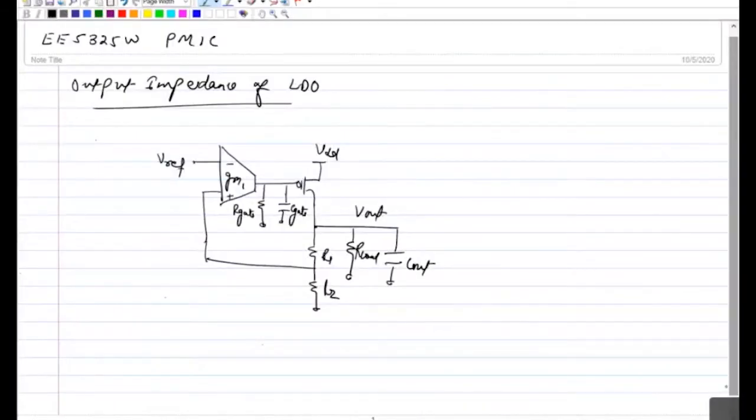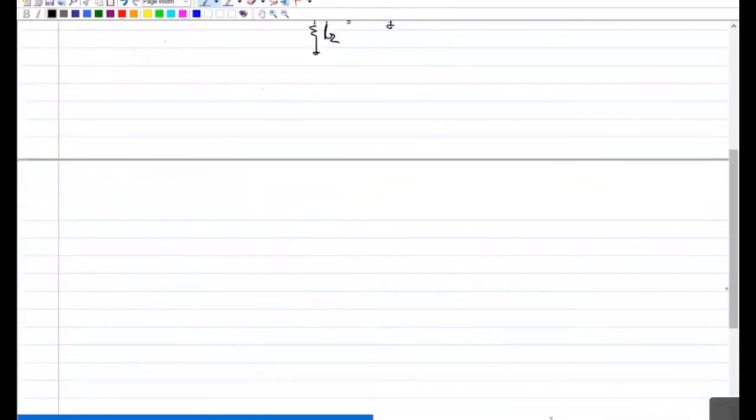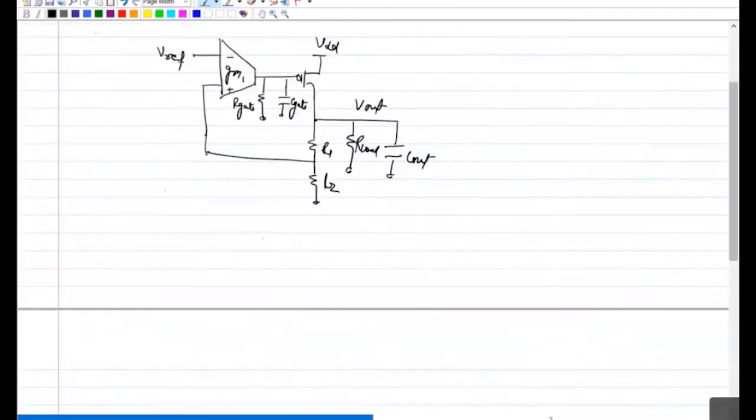Okay, so we looked into the first order impedance basically in the feedback, and what we saw is that at DC it will be suppressed by your loop gain. So whatever the feedback gain you have, it will be suppressed by that. So DC will be like beta A naught, where beta A naught is nothing but your loop gain.